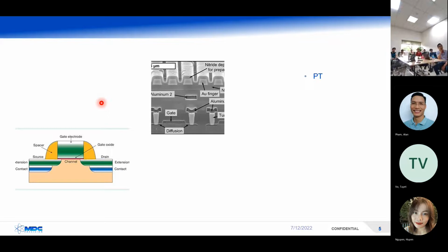So what we do: this area is treated with certain little particles, chemistry, to make them conductive. This area is made essentially to be either conductive or not conductive. It's structured such that when this is turned off, a positive charge moves up into this channel and the electrons can't flow through. When we put a voltage to this electrode, just like when I flip that switch, it forces the positive charge down and the electrons go, yay, I get to go across over here. That's how it turns on and off.